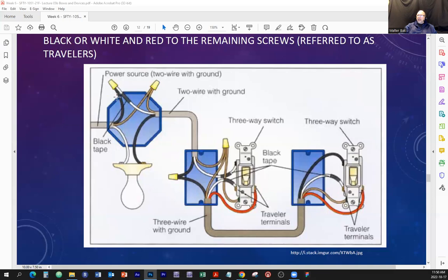So here's a pigtail right here that extends the hot. Here's a pigtail that extends the bonding wire, not the other hot. Yes, that's a bonding wire. Except it doesn't look like it's green, but it should be. Or maybe they are trying to point out that it's a bare copper wire. So they're trying to put the copper color.